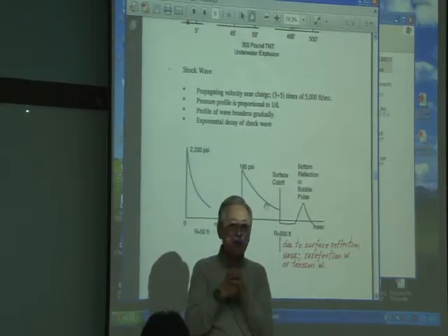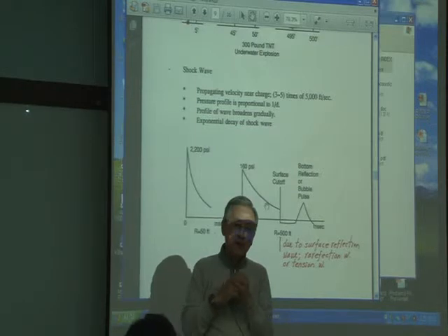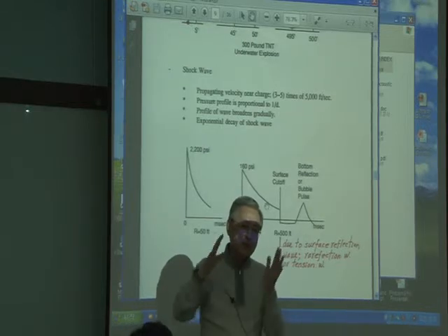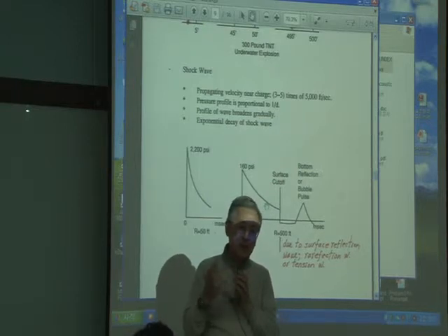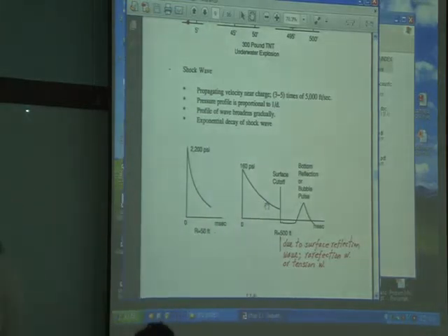Water is not capable of being pulled, but it has a very small resistance. Again, at 3 or 4 psi it can break off, but that's not greatly meaningful. So a rarefaction wave is the wave pulling the water. In this phenomenon, I'll do a little bit on this.